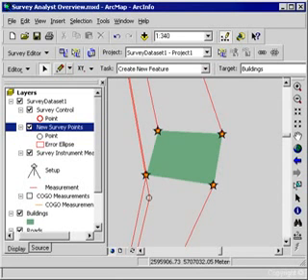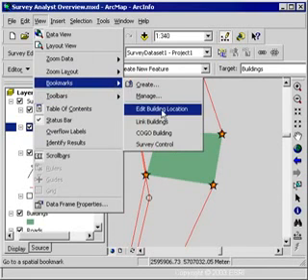So what we've done so far is we've selected one building, manually identified the links, and moved it in coordinate space. We selected 2 buildings and had Survey Analyst use a batch process to identify links for me. And when there was a possible error, the conflict window allowed me to resolve that error. And in this particular case, we just added a new building, totally from survey.